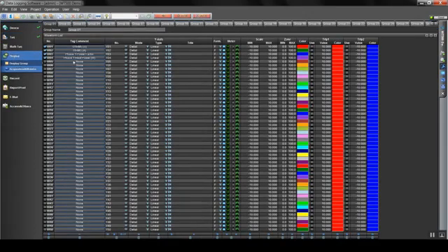Lastly, I will go to the display and confirm all tags are set up to be displayed on the GA10 graph. I will title it Phase 1 Power. Now I'm going to adjust the min and max scale. These settings may not be entirely correct until we actually see the data coming in, but I just wanted to highlight how to be able to do that.